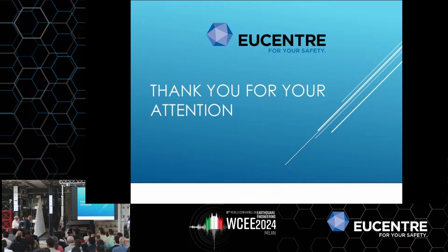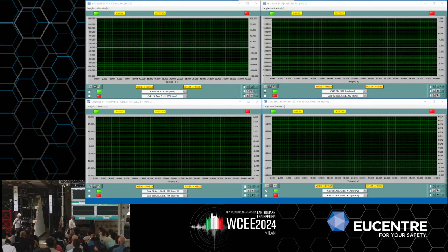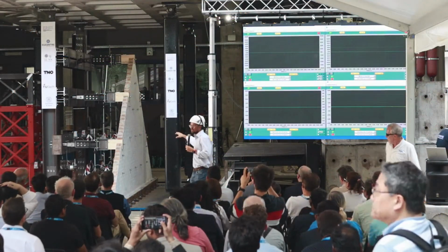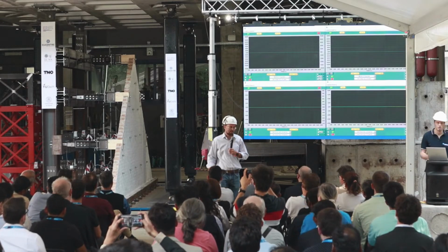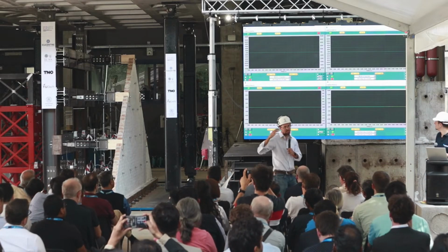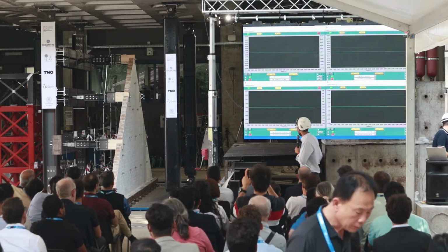So we detected the cracks. Something is happening because we noticed a lot of cracks around the joist. We noticed some horizontal cracks in the specimen, and the behavior is going really into higher nonlinearity.